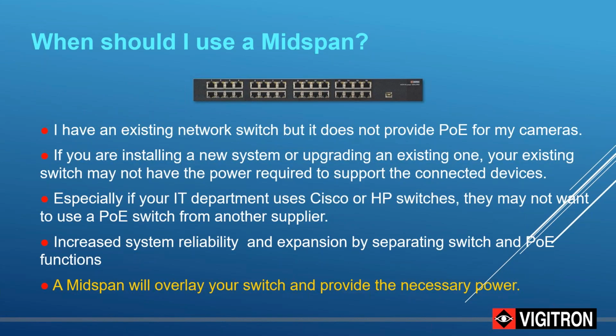When should I use a midspan? Well, there are actually many considerations. The first is I have a network switch, but it doesn't provide PoE for my cameras. Many of the standard network switches that are out there only go up to 30 watts a port. And as we're mostly familiar with, lots of cameras and devices these days in our security environment require more than 30 watts, so a midspan, provided the midspan itself does provide more than 30 watts.